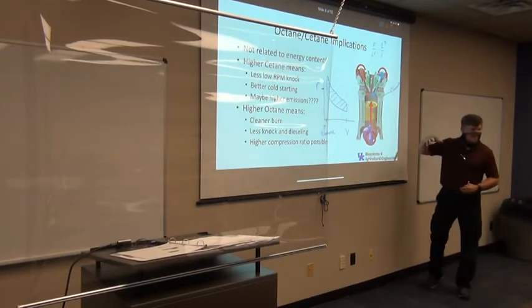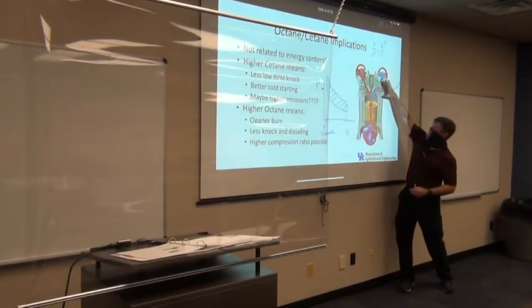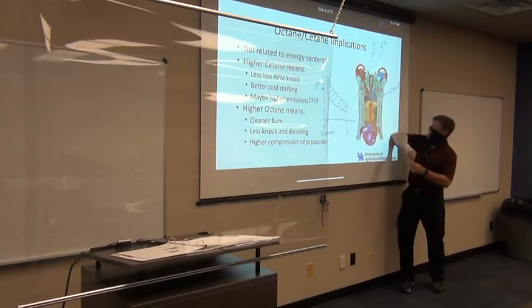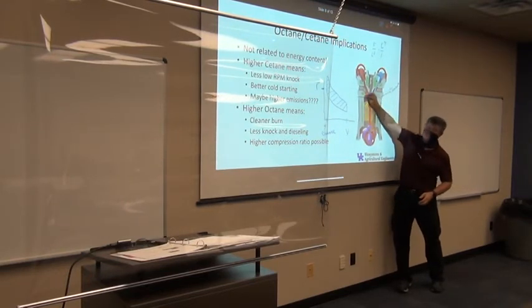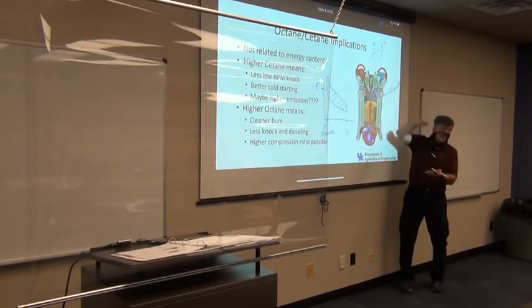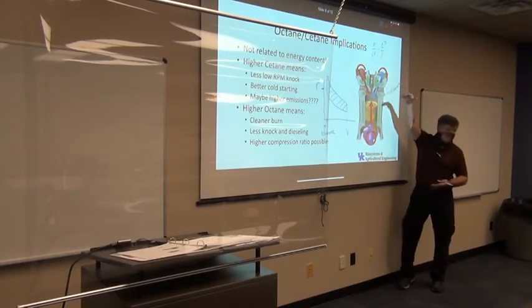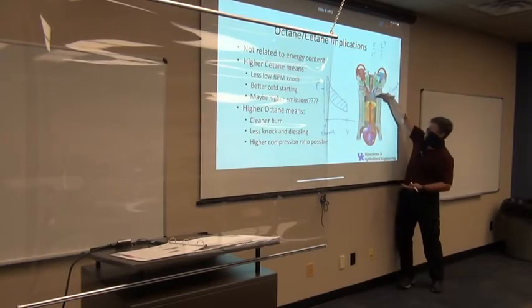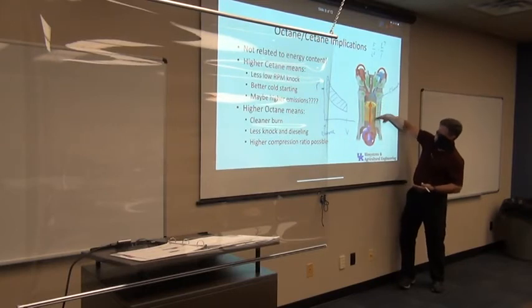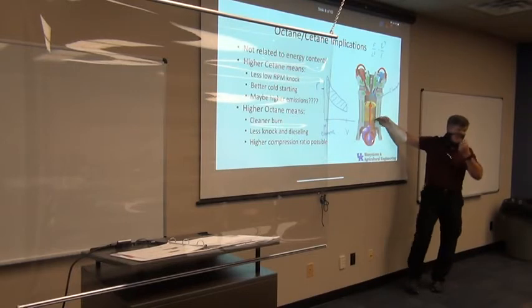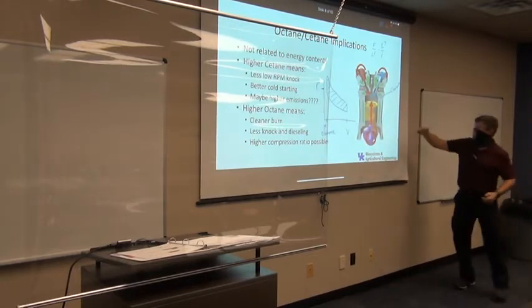So the head piece, the head. The head is the top that bolts on. So you kind of see a joint right in here, right? The top of that engine will actually bolt on, and all the hardware is not shown there. But this top piece will bolt down onto the cylinder block. So this is the block with the cylinders in it. So what we would do is shave the head.